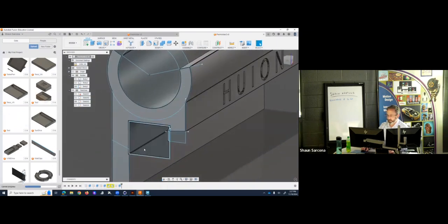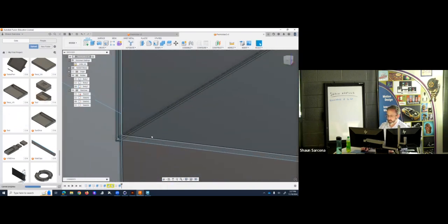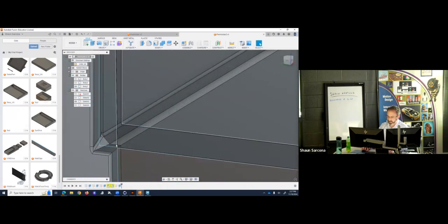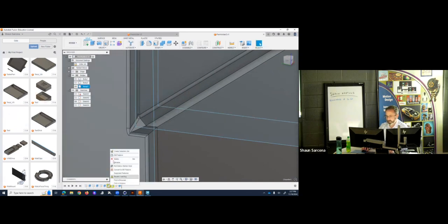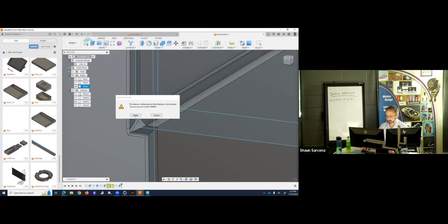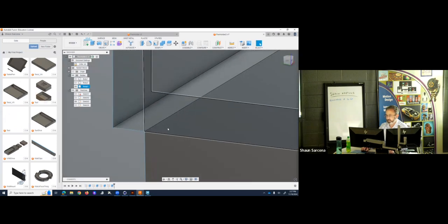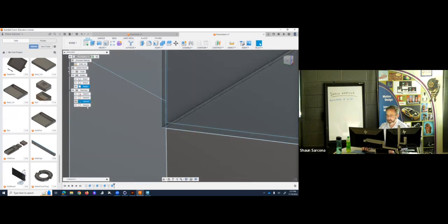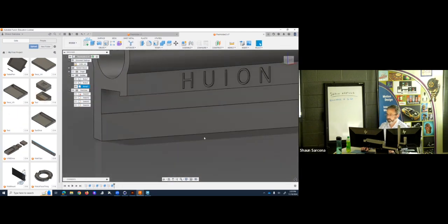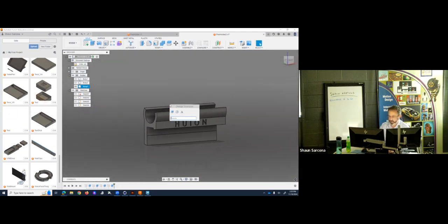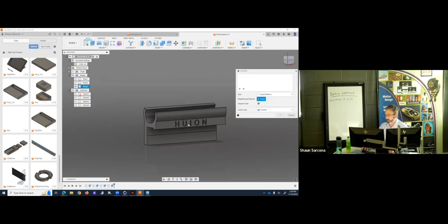Okay, now why did it freak out? Well, when I drew the next one, I did not like this new chamfer area that I've created. So you'll see I get a couple errors down here. So maybe I want to delete those. And let's hide our sketches. And then we can go back and add our chamfers again, or maybe just fillets, just straight up fillets.